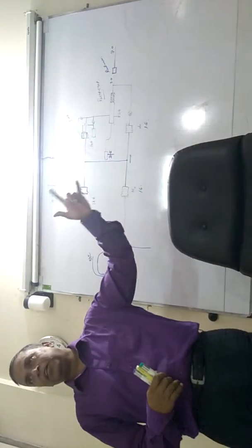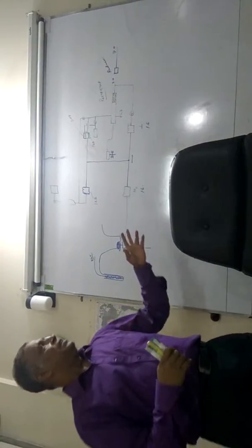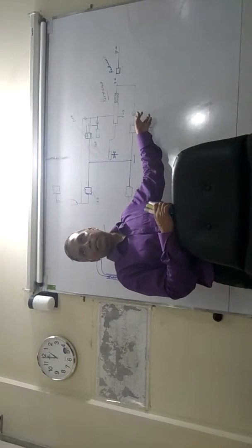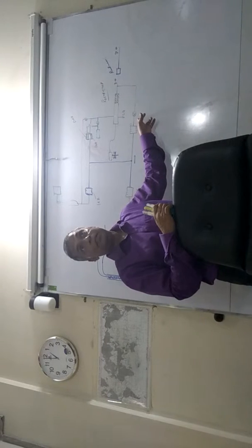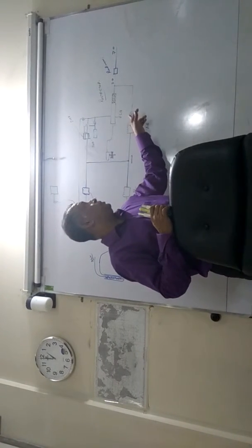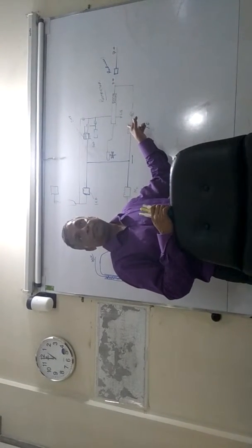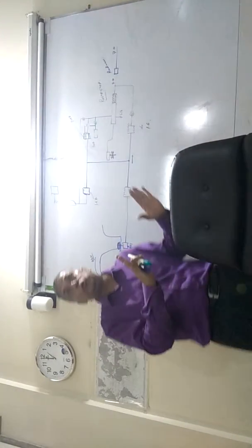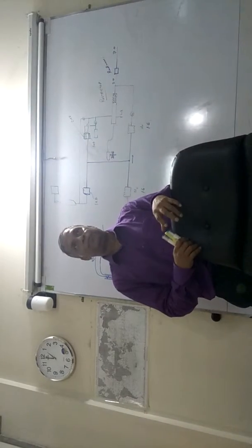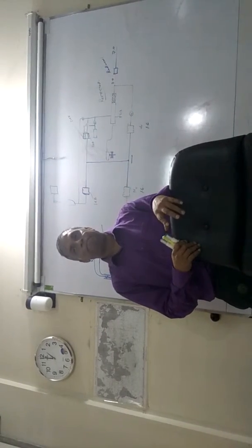That is one thing. The second thing is, this valve is not only supplying, it's also partly draining. Understand? So when it is pushed, still it will maintain that pressure. The excessive pressure that is created by the push will be drained out. Okay?